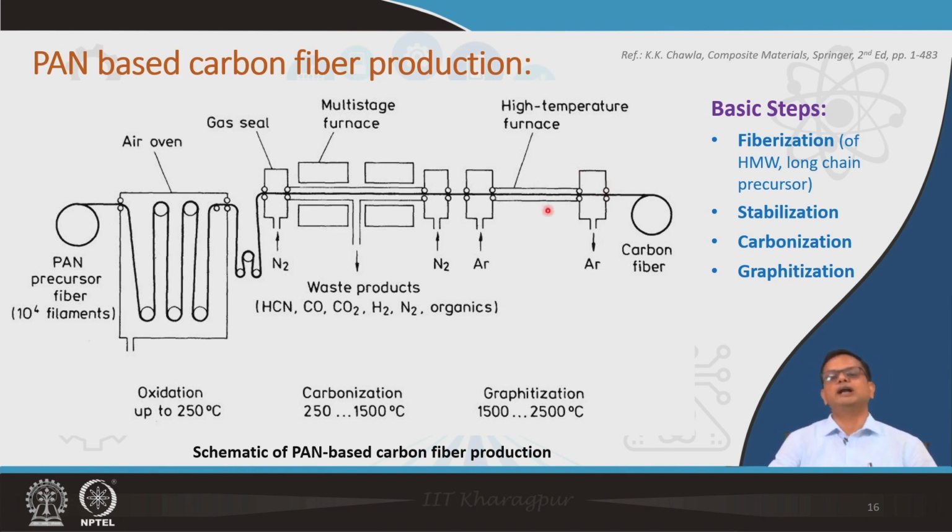So, then you go for a higher temperature. Okay. Here, even if you get rid of the non-carbonaceous elements, you may not get all the hexagons. Okay. There could be heptagons or pentagons. Okay. So, to get rid of those structures which are not hexagons, this high temperature process, or graphitization, is applied. Okay. Let me show you the molecular structure and the change in the molecular structure, and I think it will be more clear to you.